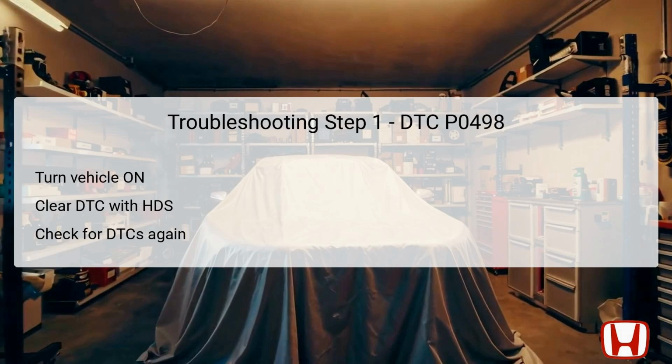If the P0498 DTC reappears, it confirms that the problem persists and provides direction for the next troubleshooting step. Conversely, if no issues are detected post-clearance, it may suggest an intermittent fault that will need further investigation. Utilizing the HDS effectively in this step is fundamental for accurate diagnostics.